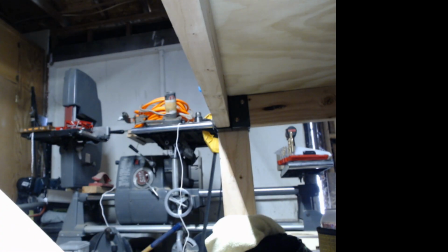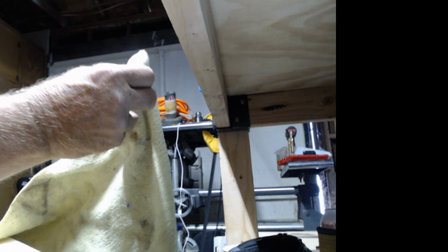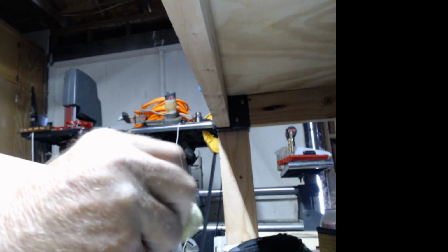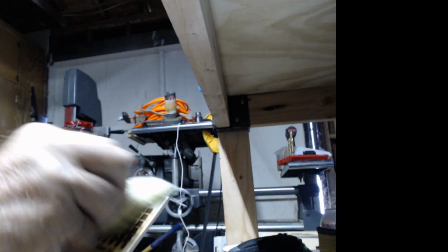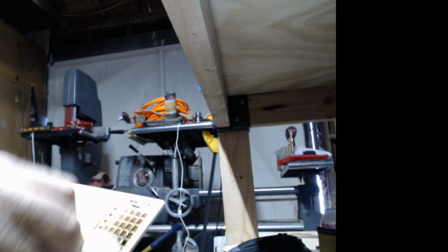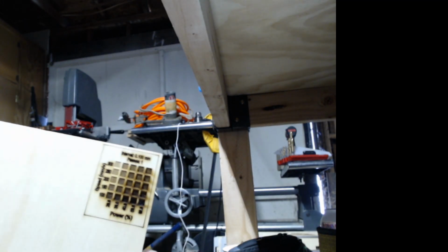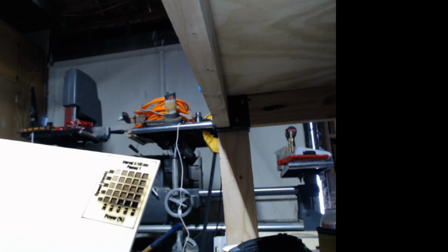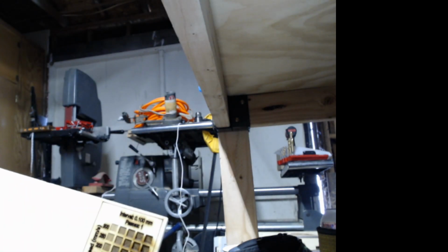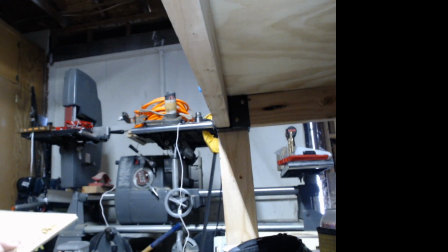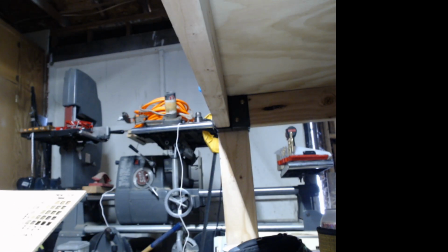Now what you can do, if you really want to look at this well, is clean it. Take this microfiber cloth here, we'll rub over it, and that'll get some of the stuff out of the actual squares, so you can see the squares a little better. You can see there's overburn on the part because the air is on. I didn't turn it off. I could have turned it off, and we can sand that down and get rid of some of those scorch marks if we want to. But it's not important because this isn't a part we're going to sell. This is just so that we can get a speed test going.